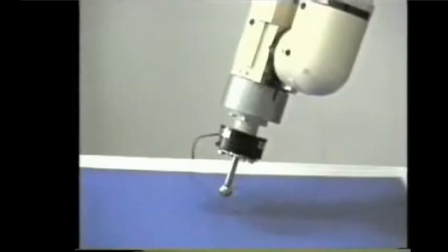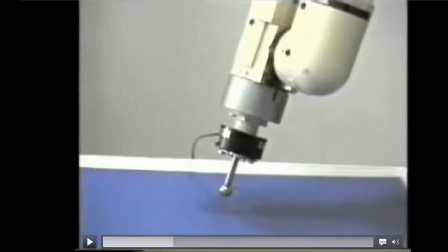Of course, when you're getting in contact, the position controller will remain unattended because you cannot really penetrate the surface, but the external force loop has an integral term, so it will apply more and more force until it reaches the desired one. Okay, so this is what happens when you're having an internal position loop, which is driven by the output of an external force loop, which includes an integral term. And here we will see the continuation.